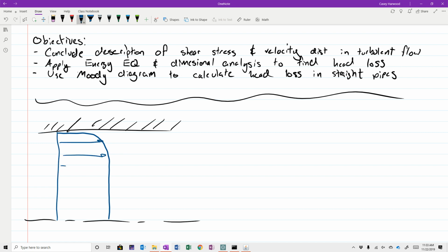And the reason for that flatness is that because of the 3-dimensional fluctuations that occur in a turbulent flow, it's very good at mixing faster moving packets of fluid with slower moving packets, and so it pushes all that momentum out towards the walls. So it's really only out here at the very edge of the flow, where it's in contact with the pipe walls, that you start to see this reduction in velocity. So if this is u of r, and here's r, this is our velocity distribution. Out here is our pipe wall.